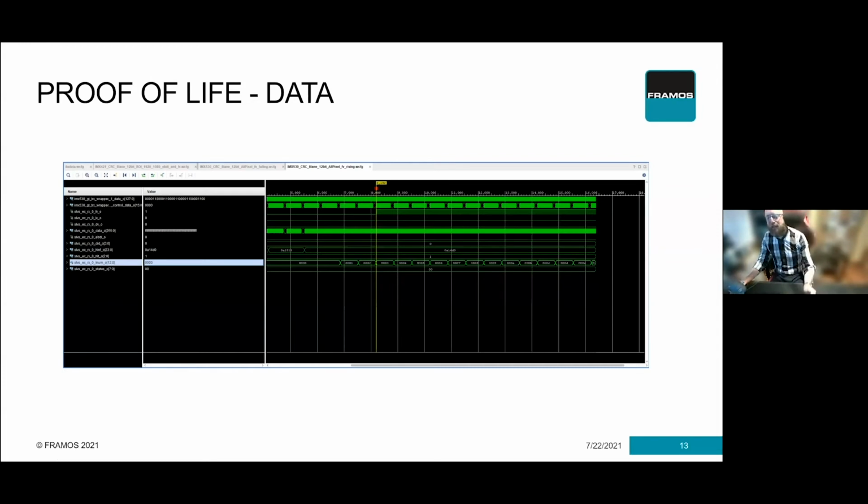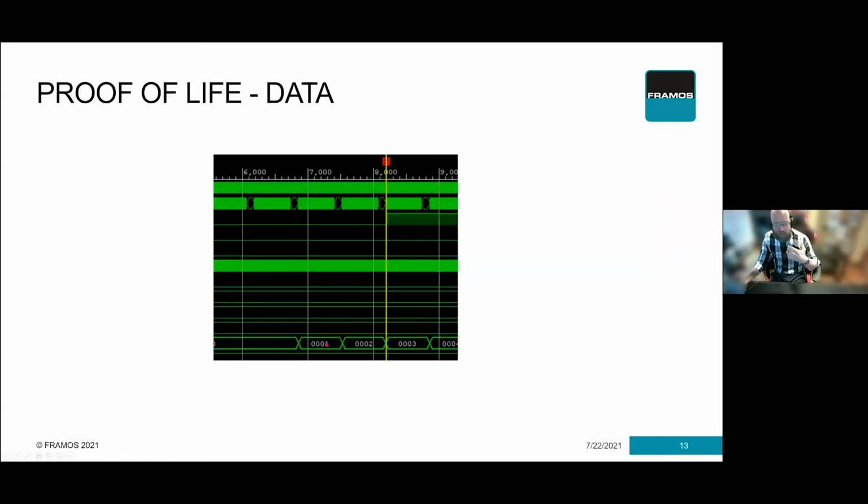Typically, I don't have access to a very fast logic analyzer, or even better yet, I'd love to have an even faster oscilloscope. But what we do have within FPGAs and FPGA designs is typically the ability to do some capture inside and dump that to a main PC. This is the Xilinx system, an ILA out of a Xilinx ChipScope. We would put known data onto that system and then just say, look, it should go 1, 2, 3, 4, etc. So we can have a look at the data as it comes in to our FPGA and verify that it matches what we expect from the output.